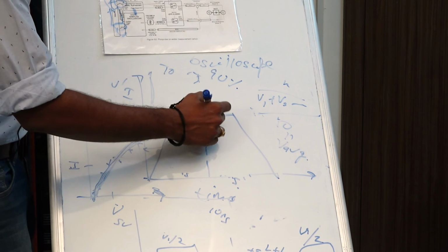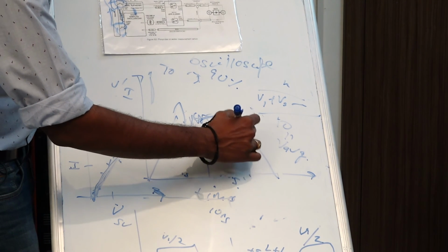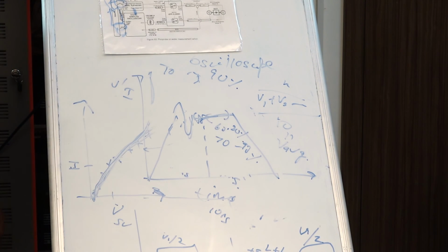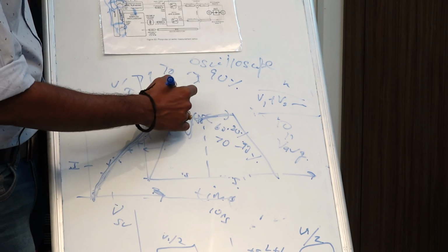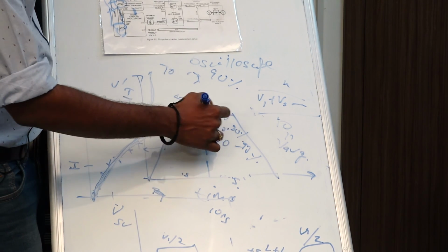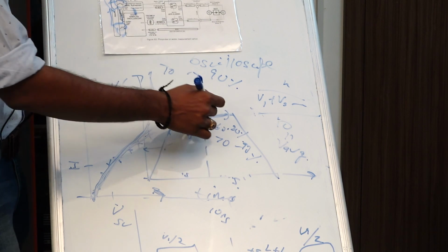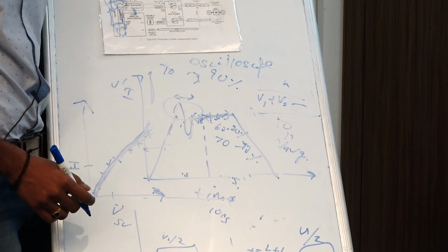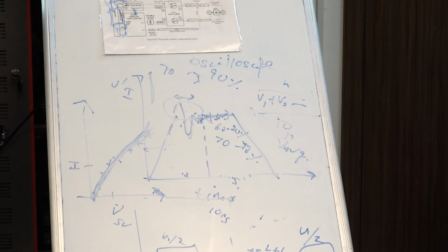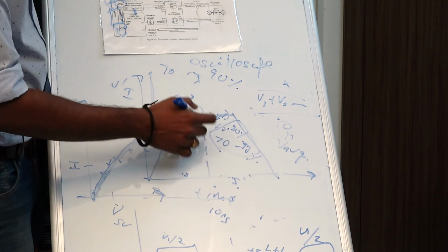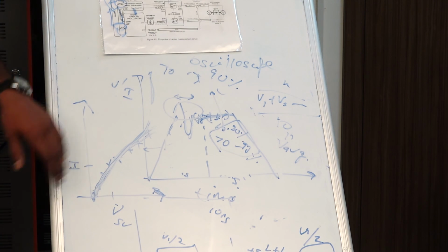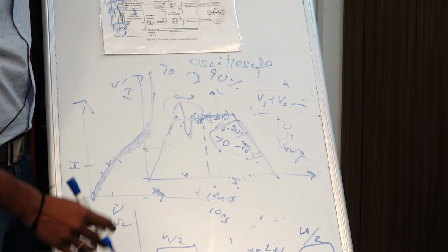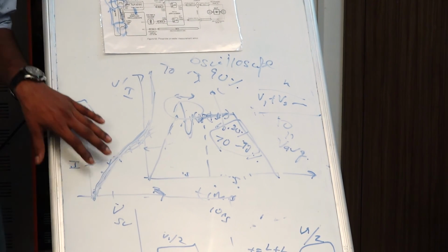The 60 to 80%, or 70 to 90%, is the time period in which your voltage waveform has settled down. All the parasitic components of the wires and cables have settled by this time. So the voltage that you measure is the actual device voltage, free of any parasitic impedances. That's the reason we use 60 to 80% or 70 to 90% as the averaging window for both the current and the voltage, so that you don't capture the parasitics, you capture only the DUT behavior. So that's why the averaging part is also important.